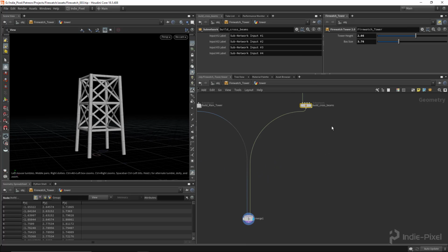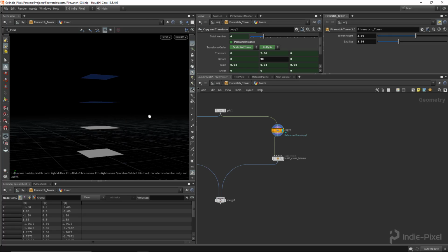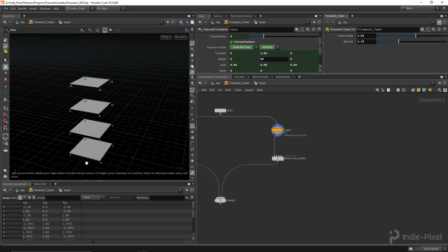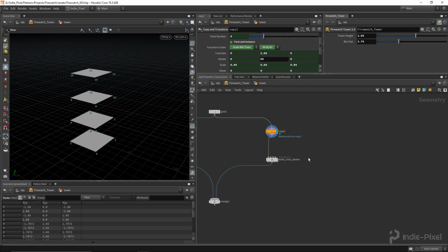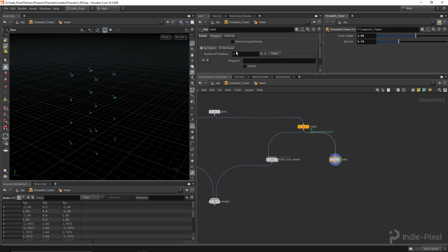Let's go and start focusing on building out the stair graph here. And so what we can do is build off of what we have right here. We have basically the spinning grid, right? So all the point numbers are being rotated 90 degrees for each one of those copies. And so we can just take another add node. So I'm just going to pull off over here like so, and do our delete geometry, keep points.